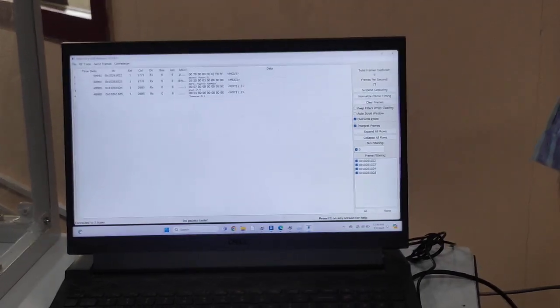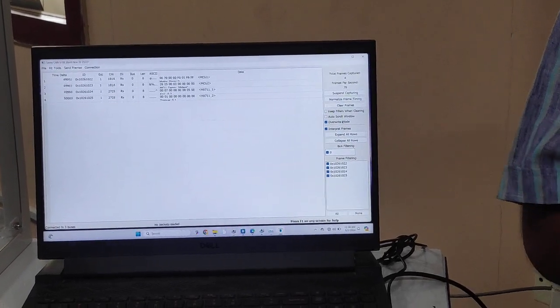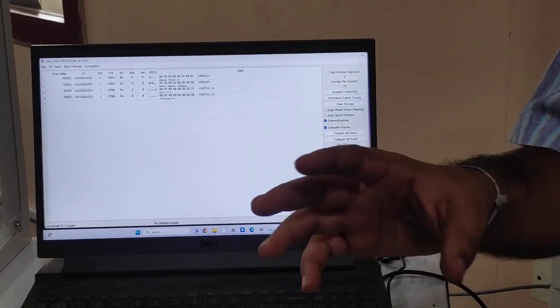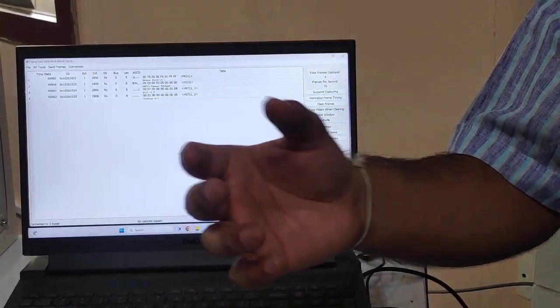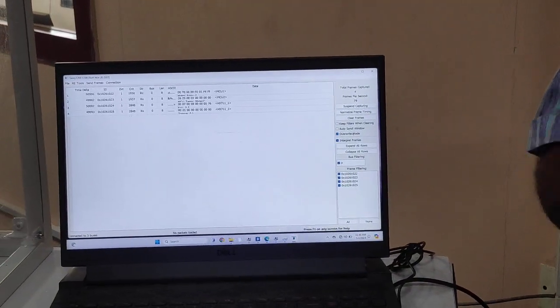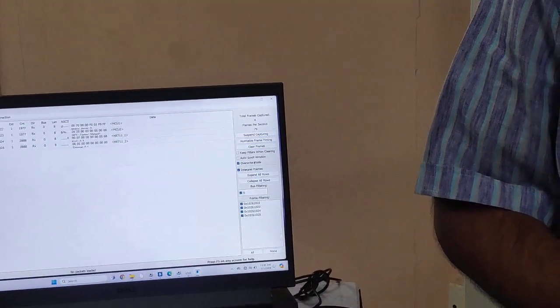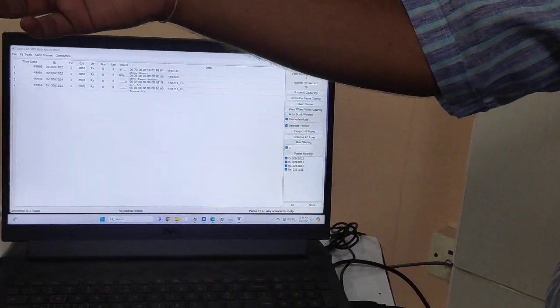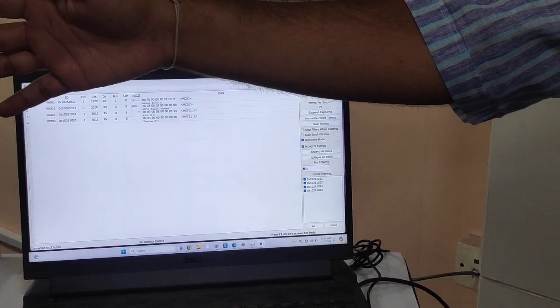So the motor vendor will give a specific data. This is the amount of current that it should draw at particular speed. So if it is drawing anywhere beyond that, it means we have to check that there are any faults within the motor. That is how we'll get to know the faults in the motor. So to do that, make sure no load is being applied.